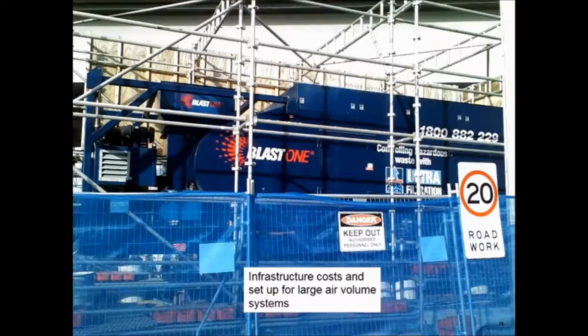The fan systems can be purchased outright for $250,000, or they can be hired. That is, what you get is a 40,000 CFM extraction fan. The exhaust air has to go through a HEPA filter system that extracts out the dust particles down to 10 microns of respiratory dust, and that size allows it to go back into atmosphere without endangerment to the individuals or the public.